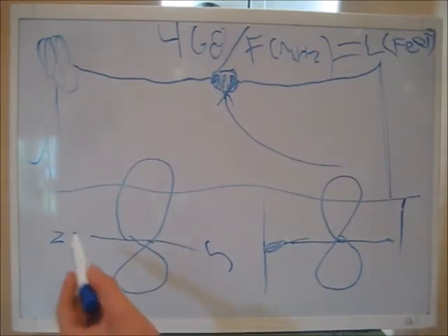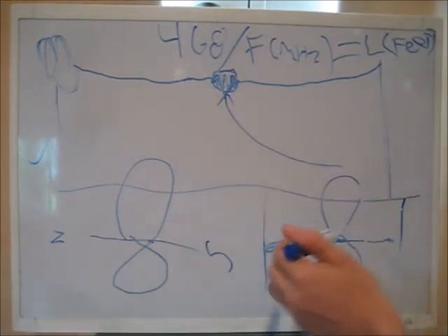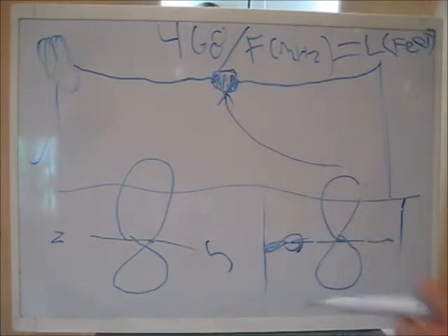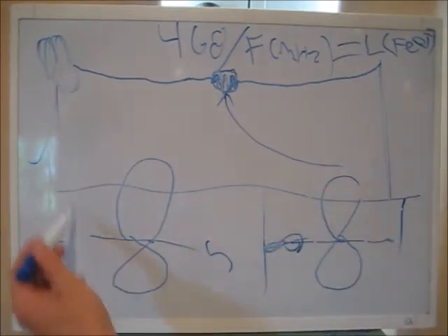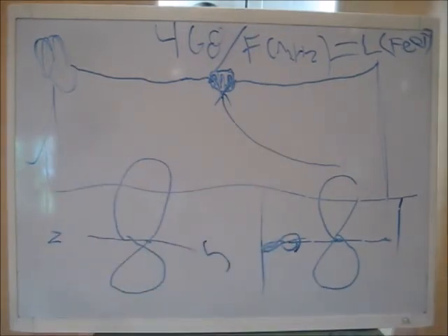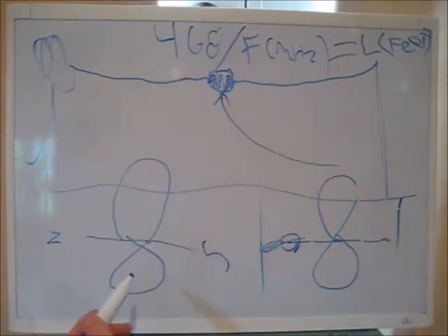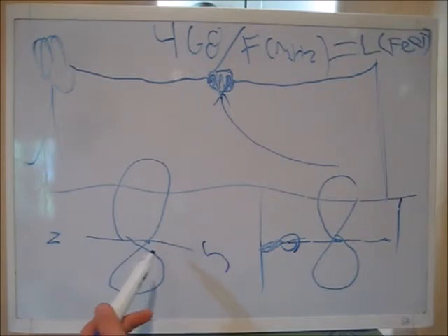Okay, now although this drawing shows that only this part of the antenna is radiating, these ends also radiate, so it's actually a much wider figure 8 than this. The figure 8 more looks like the size of the antenna. The whole antenna is radiating, but they radiate broadside. So if your antenna is running north-south, your signal is going out east and west. So that gives you an idea of how you can work stations.